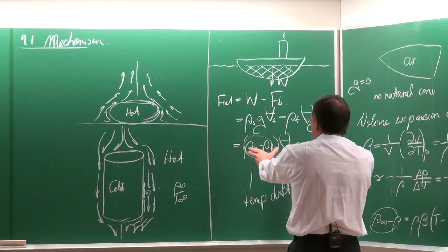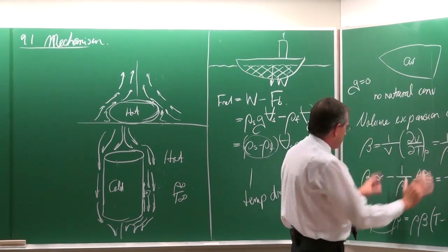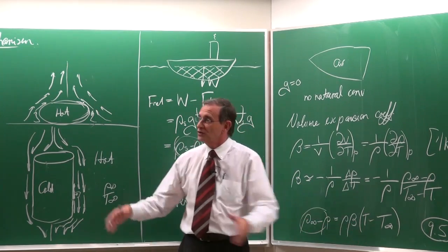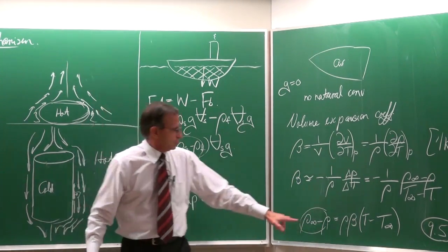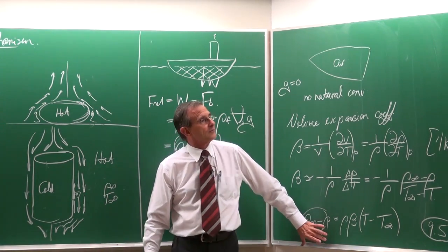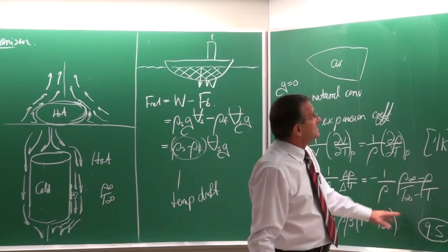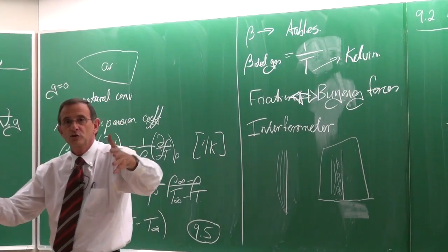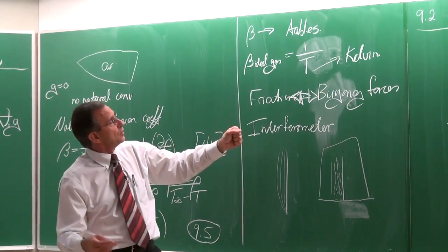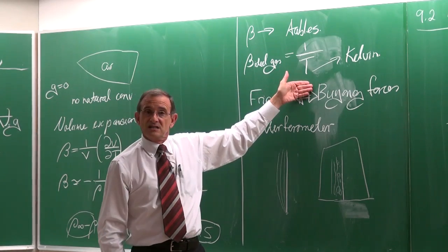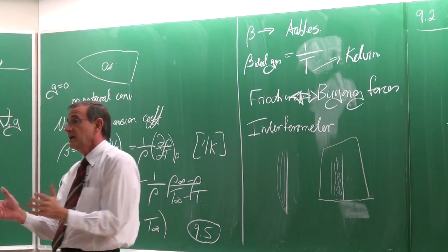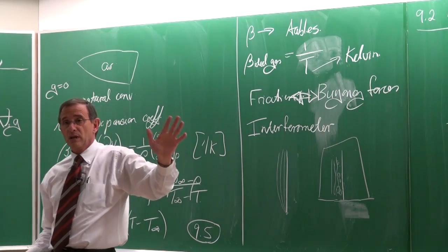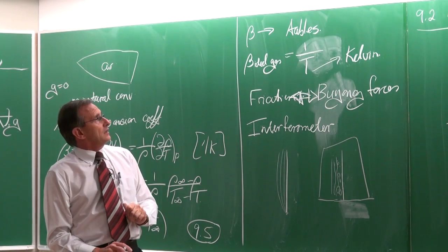Right, now this effect, this density difference, in terms of thermodynamics, we can go and derive it as approximately something like that. So here it shows the temperature difference causes this change in density. That is what this is all about. However, to get the beta can be problematic. If you've got tables, it's not a problem, or if you've got computer programs, you can calculate it. You can also, if you make the assumption that the gas that you work with is an ideal gas, say it is approximately 1 divided by the temperature in Kelvin. In many cases, it is quite an accurate calculation.